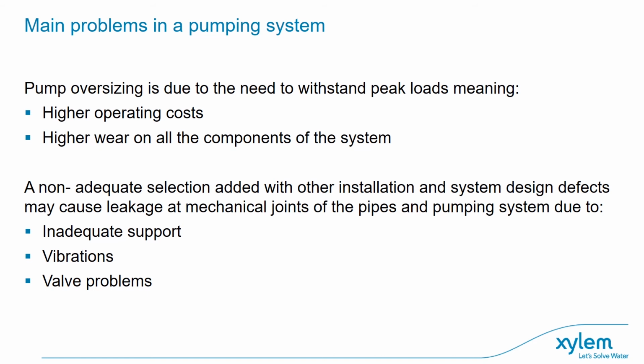Pumps are rotary equipment and are subject themselves to wear, erosion, not to mention axial thrust, cavitation, leakage. Many problems may derive from a non-proper selection and operation.